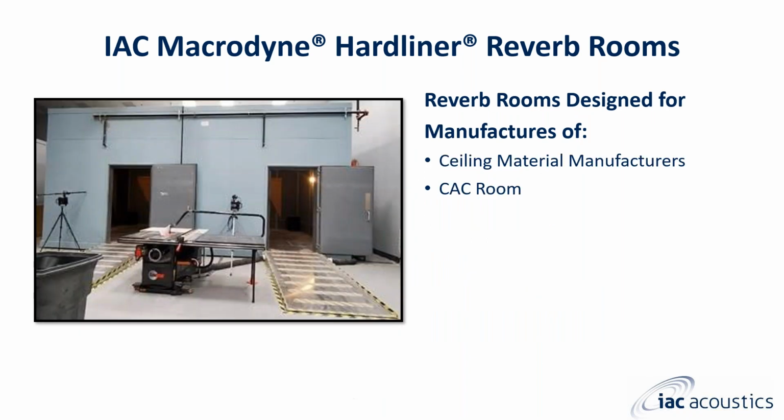In this slide here, we show what we call a CAC room, or ceiling attenuation class, whereby two adjacent reverb chambers, modularly constructed of the IAC Moduline system, have an open ceiling across both chambers, whereas the manufacturer of the material inserts the ceiling material and then tests the relative attenuation between the two chambers through the ceiling material.